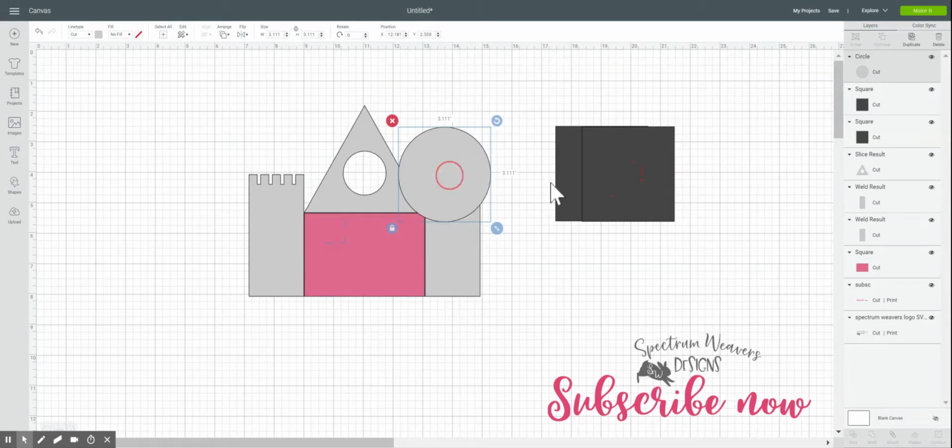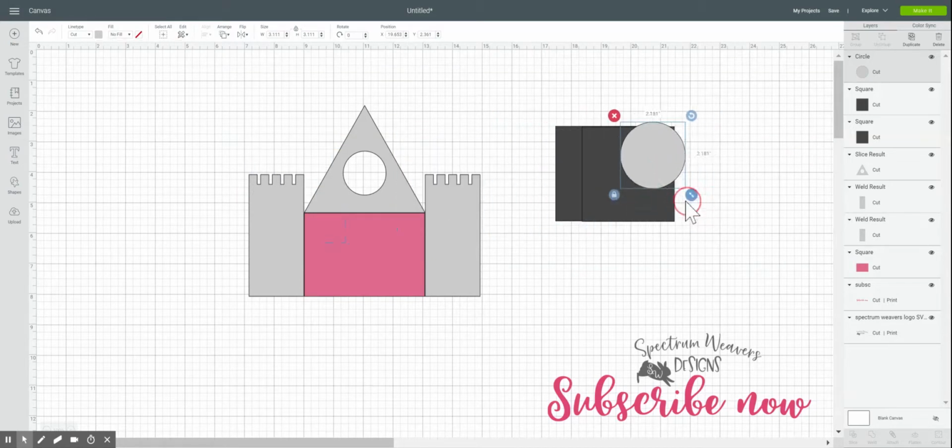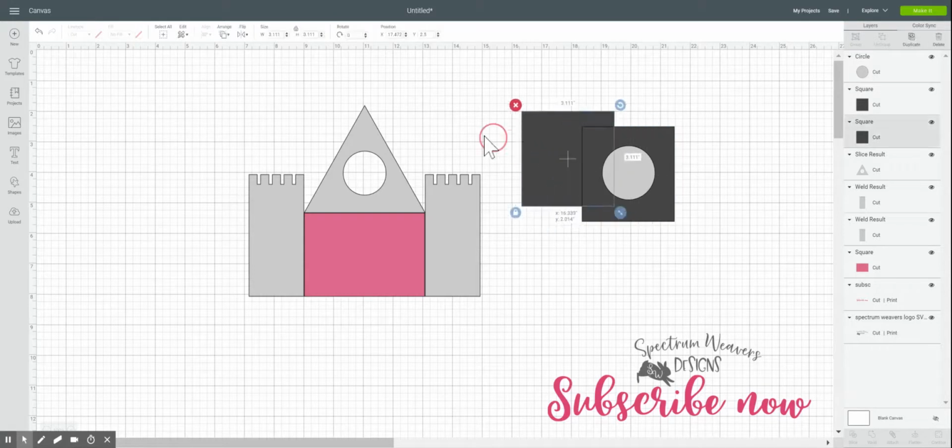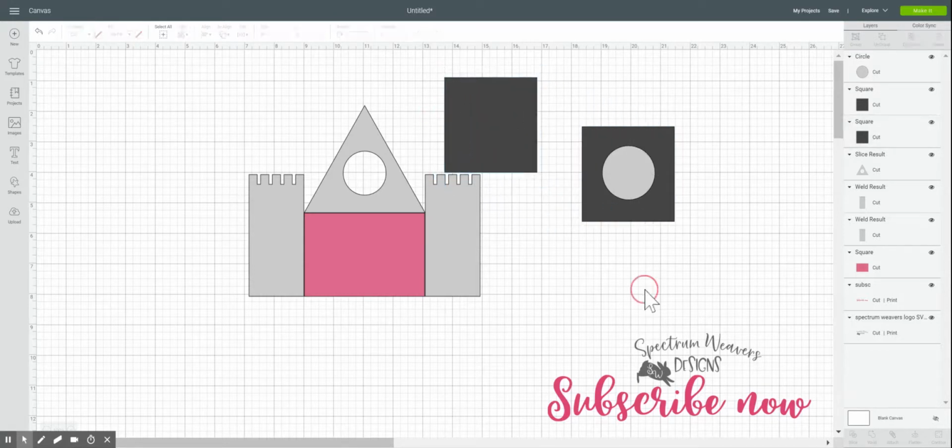Say I want to take this circle and slice it out of this square right here, right? So I'm going to select all of this information over here. I'm going to select the two boxes in the square. I'm selecting all of that, right? Slice is not lit up. Slice isn't lit up because I have two boxes in the square. That's three items. Now, if I move this one away, I can just select these two and now slice will be lit up. Okay.